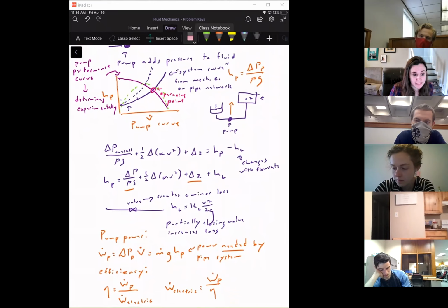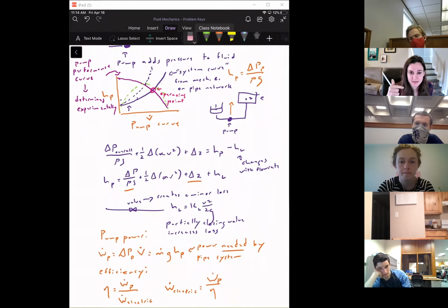So not really. You can have a different model of a pump, or you can have the same model, and a lot of times the same model will have different sizes of impellers inside of it, because a centrifugal pump has impellers spinning around inside of it. So you can order the same model with different impeller sizes. I don't think people normally switch them out. I think you just buy it one way or another. So the only thing you can really do to change your pump performance curve is get a different pump.